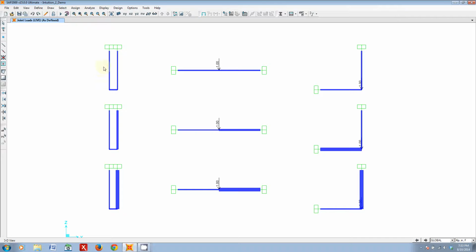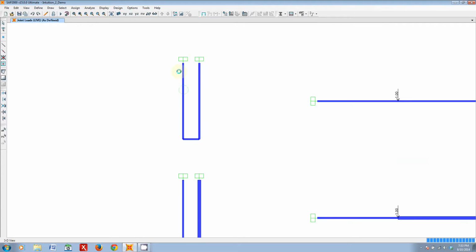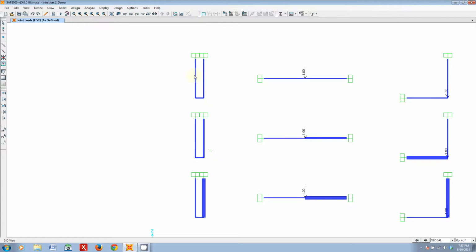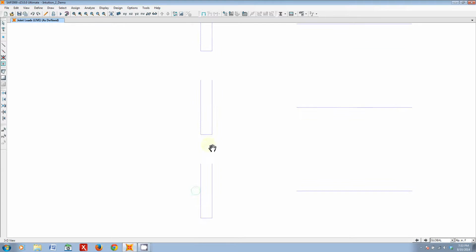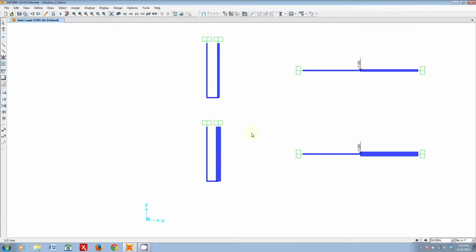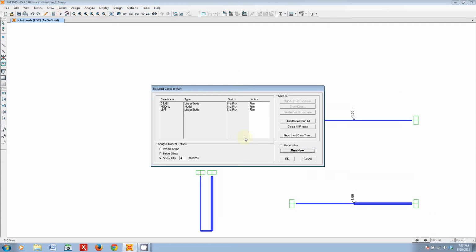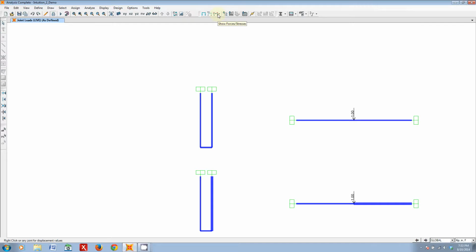The first example is basically just two rods in parallel hanging from a ceiling, fixed at the top, and then there's a unit load applied right in the middle. We're going to pull down on that and see how the load gets transmitted through those two members. I have a couple different cases: in the first case both rods have the same area. In the second case, this rod has a little bit more area, so it's a little chunkier, and in the last case we've got a really thick one. Now let's test it out. Run my model and see what happens.